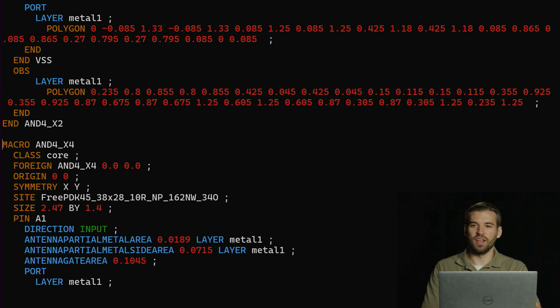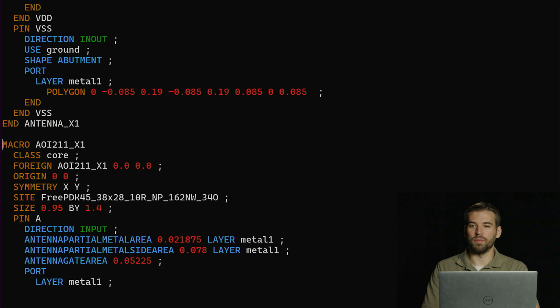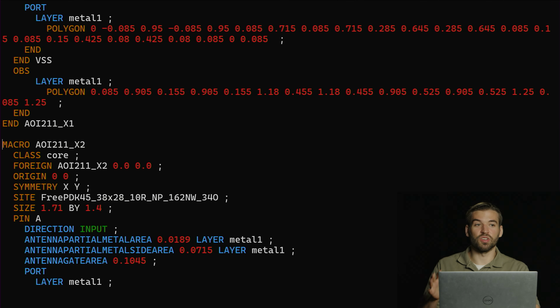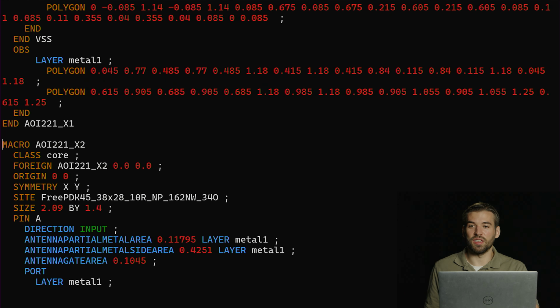You can see there's AND 3 gates, so those are 3 input AND gates. You can see that there's other kinds of gates that we haven't talked about, like an AOI, which is an AND OR and then inverted, which turns out to be a useful gate in many different logic synthesis applications. For certain types of structures, they end up being used a lot, so they're appearing in here.